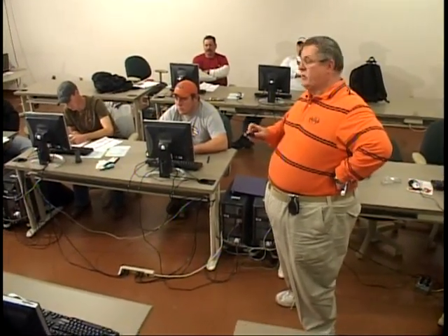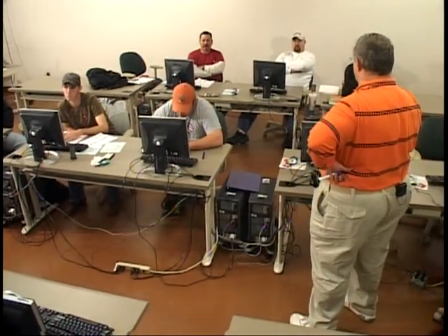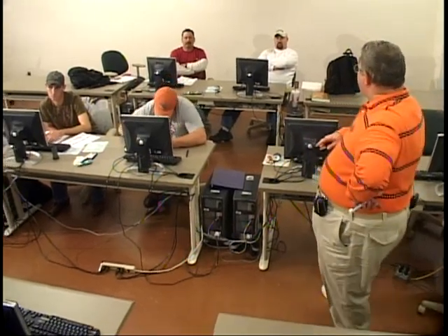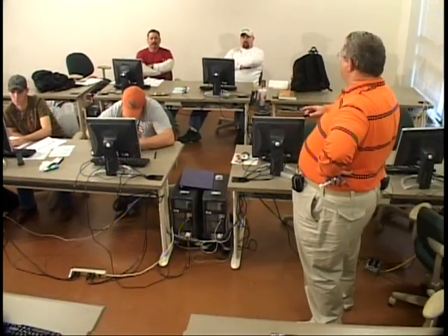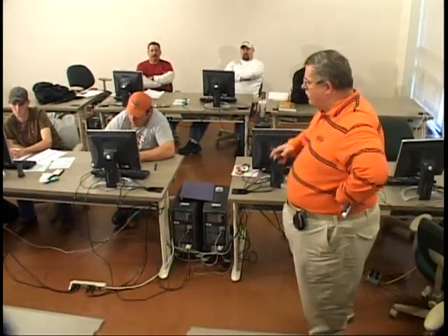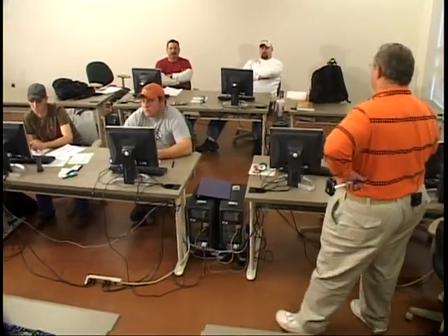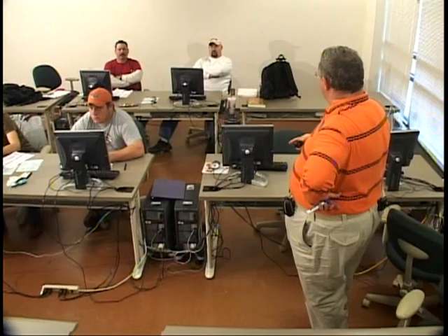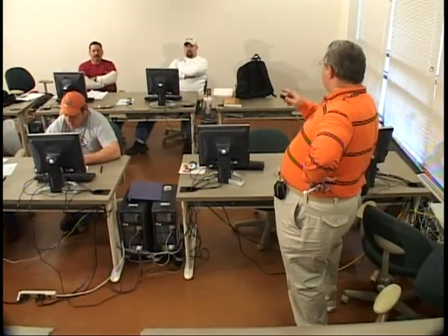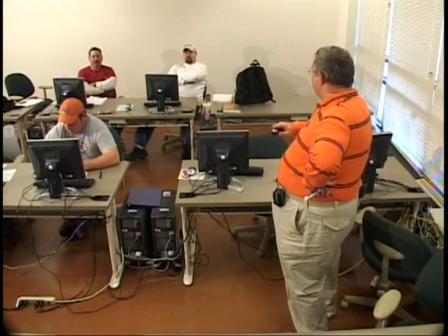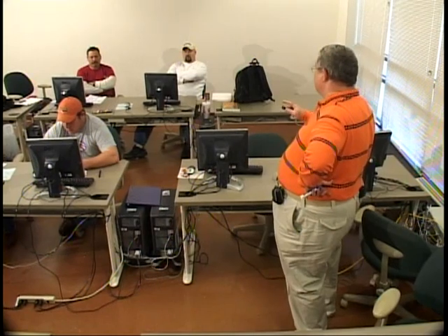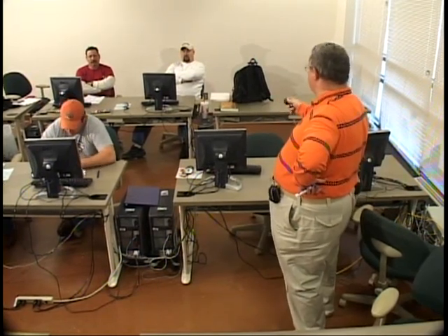Other things that you'll need to show on your survey are overlapping descriptions. If you have a description, which you will have for your survey, you lay out your survey according to that, but the adjoining survey may have been performed on a description that was not in agreement with the descriptions you had. We as surveyors express our opinion as to what is a proper location of that property. If there's a disagreement between two property descriptions, that's a dispute that will be resolved by the courts.